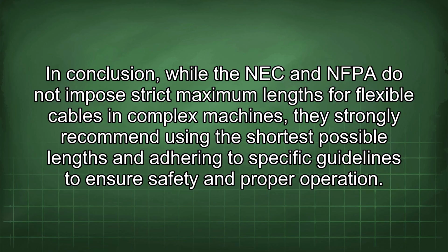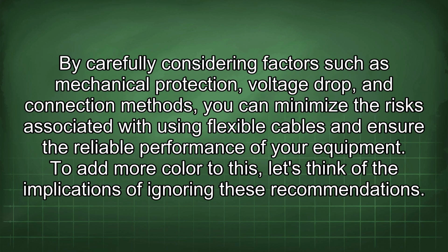In conclusion, while the NEC and NFPA do not impose strict maximum lengths for flexible cables in complex machines, they strongly recommend using the shortest possible lengths and adhering to specific guidelines to ensure safety and proper operation. By carefully considering factors such as mechanical protection, voltage drop, and connection methods, you can minimize the risks associated with using flexible cables and ensure the reliable performance of your equipment.